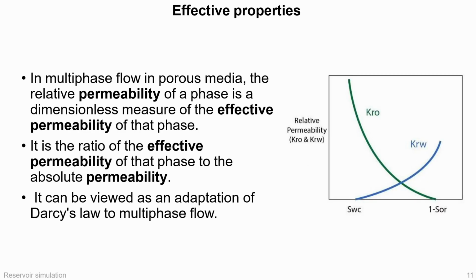This slide introduces relative permeability, which is central to multiphase flow. In a reservoir, oil, water, and gas share the same pore space. Therefore, each phase does not flow as easily as it would if it occupied the rock alone. Relative permeability measures the effective flowability of one phase relative to the absolute permeability of the rock.